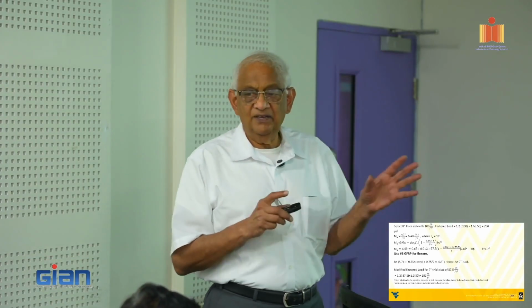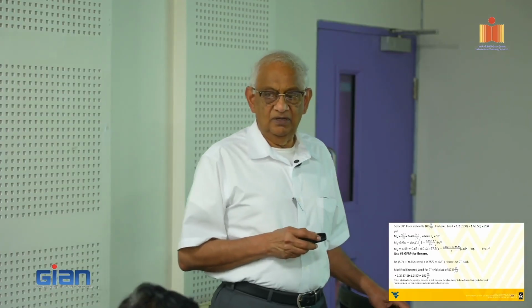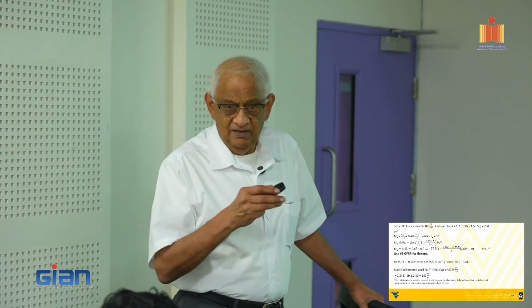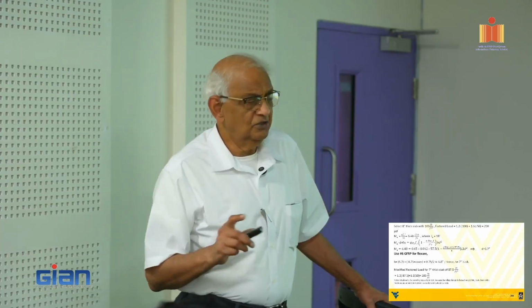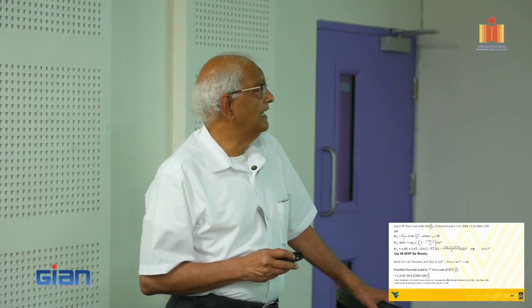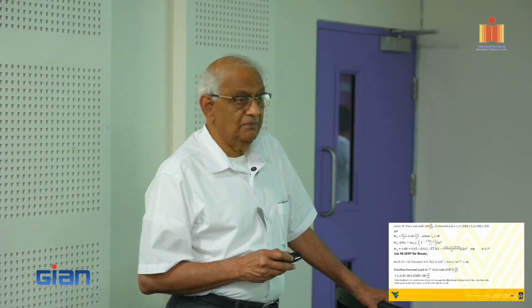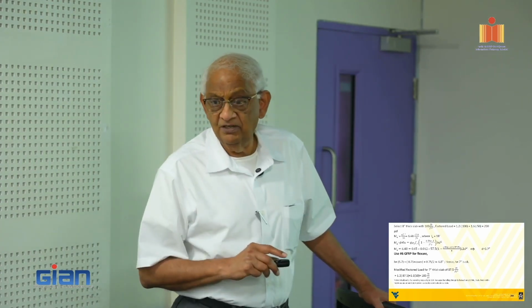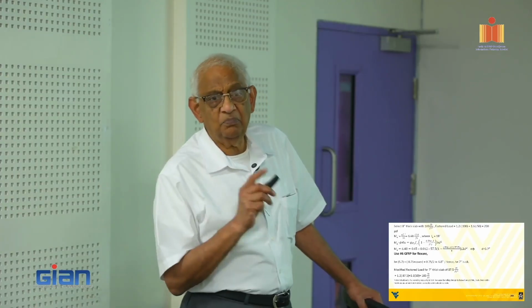That's where you need to balance this out, push it as much as you can by, you remember I told you a few minutes ago, reducing the depth of the concrete. Of course, you can only do it so much. So we're selecting an 8-inch thick slab as opposed to a 12-inch thick slab when we did the tension control. That is the point, isn't it?